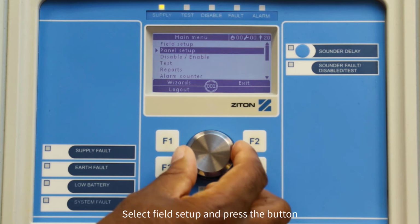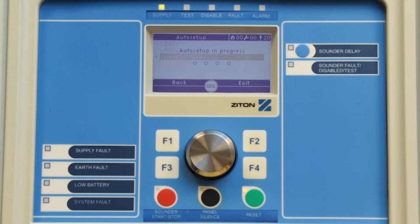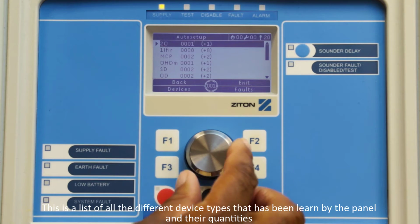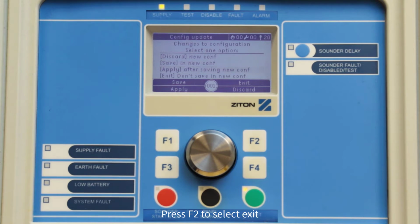Now select Field Setup and press the button. Select Auto Setup and press the button. Then select All Loops and press the button. Once the auto setup has completed, you will see the following. This is a list of all the different device types that have been learned by the panel and their quantities. Now press F2 to select Exit, then F3 to select Apply to complete the process.